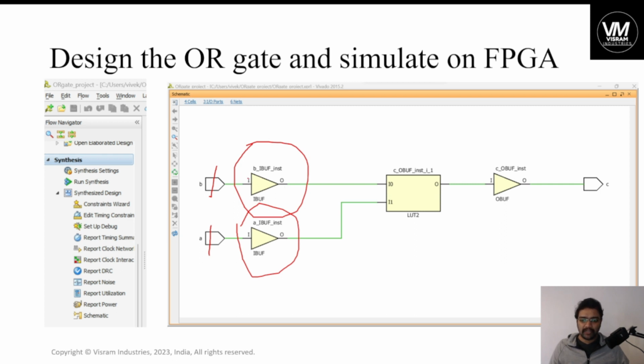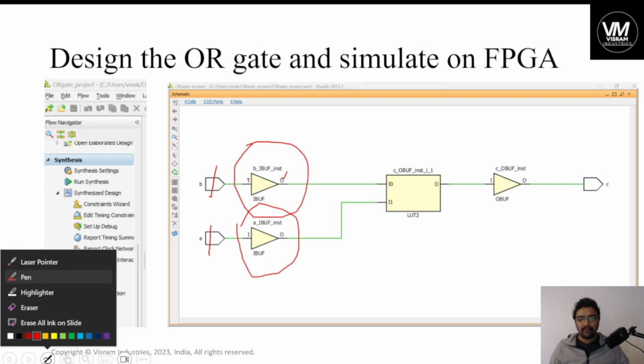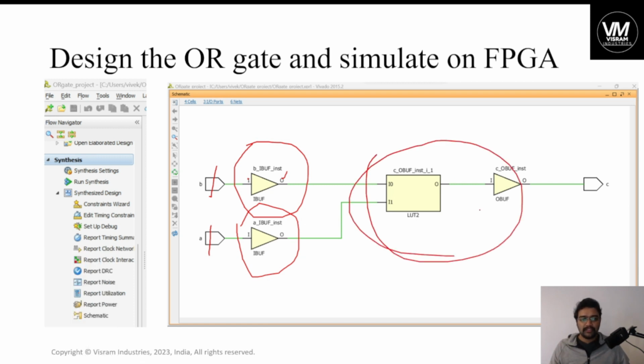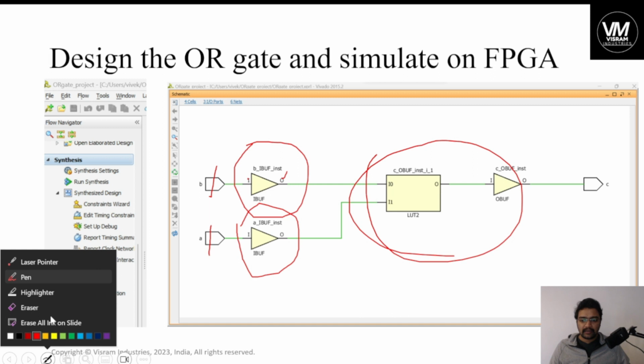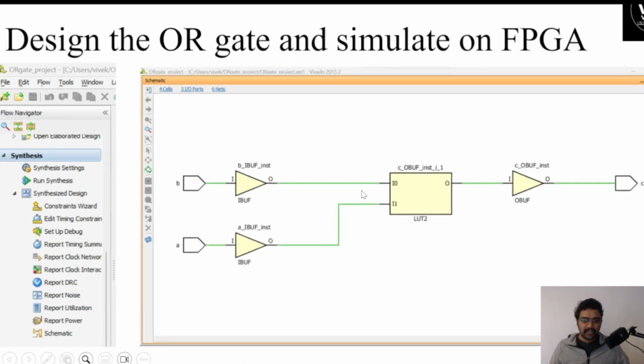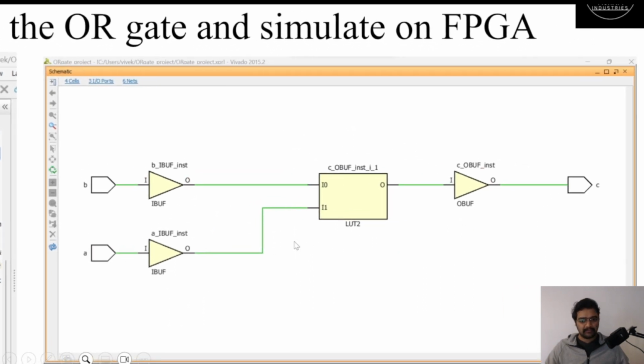So if we give 1, it will take 0, and if we give 0, it will take 1, until you enable the buffers. So it's a predefined element before the port, because if a high voltage or high surge comes into the port, it shouldn't ruin your processor. So every element inside it has a protection in it. So that is the use of it. Why do we need buffers? Such a simple explanation.